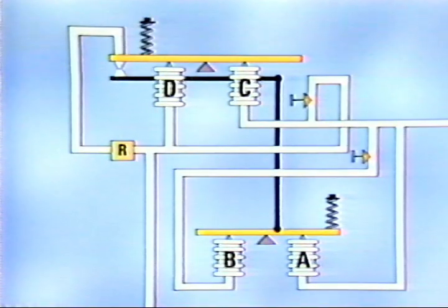First, let's see what's similar. Input enters the controller through this port, and output leaves the controller here. This controller has an input mechanism, which is one of 4 bellows. It's referred to as the A bellows. It also has an error detector, a flapper nozzle arrangement, and an output balancing mechanism,